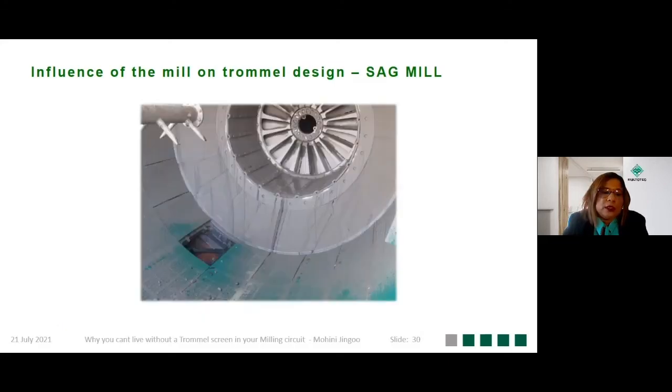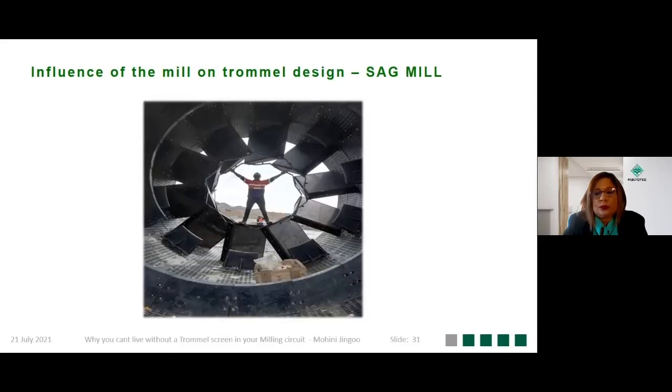Here as well, you can see there's a large step from the trunnion to the trommel, and Multotec needs to be able to model this exit slurry trajectory when we design the wear bar and when we are optimizing this layout. These were baffle plates for an initial design on a copper mine as well in Zambia. In the previous slide, it proved difficult to maintain. The customer thereafter removed the baffle plates and the trommel is working exceptionally well.